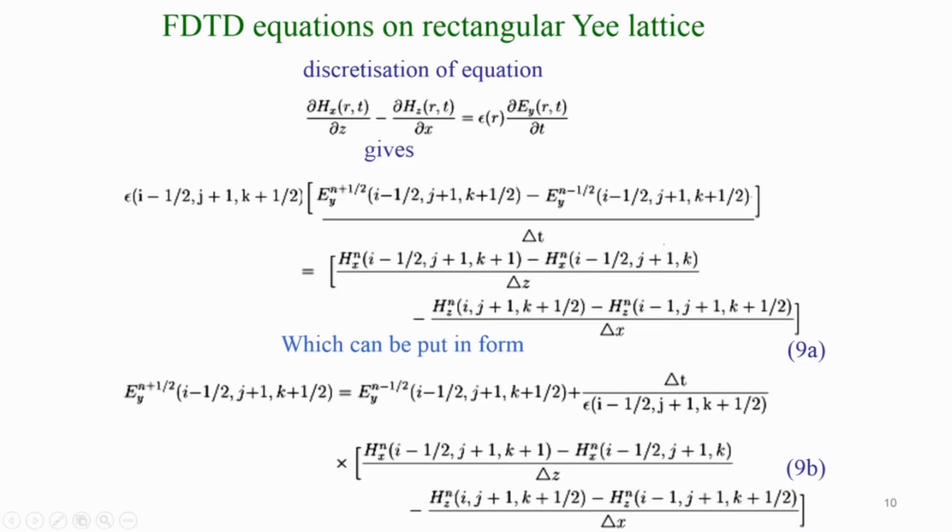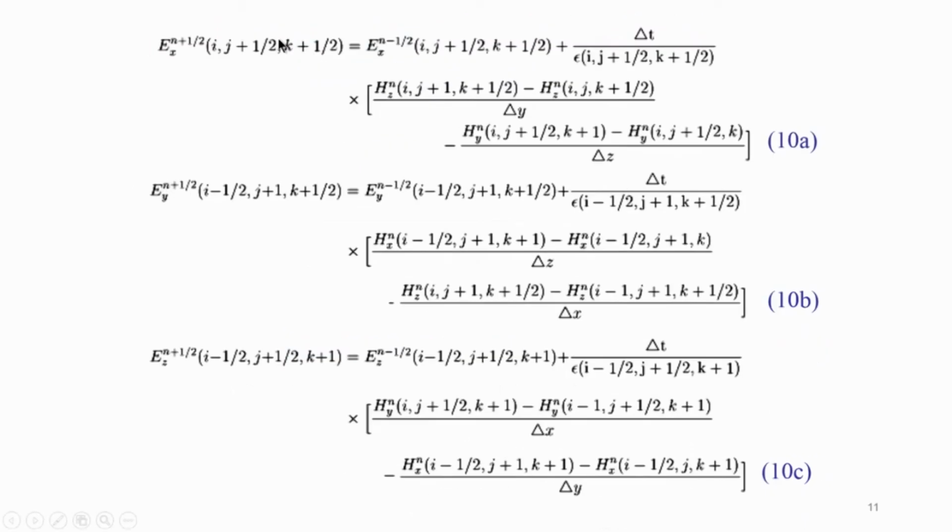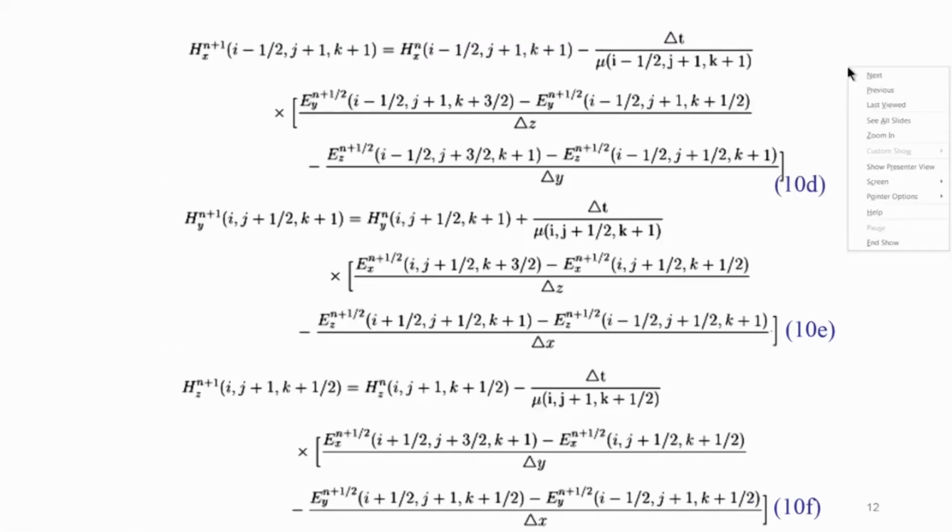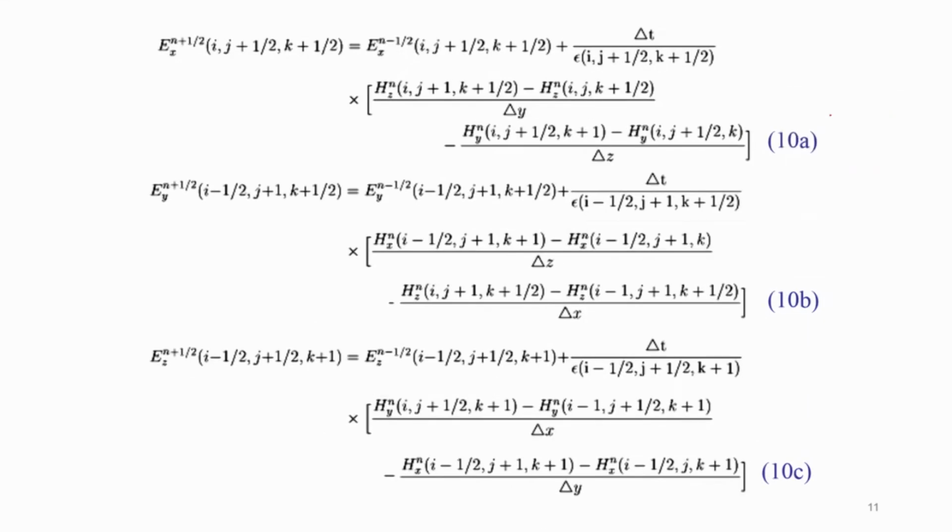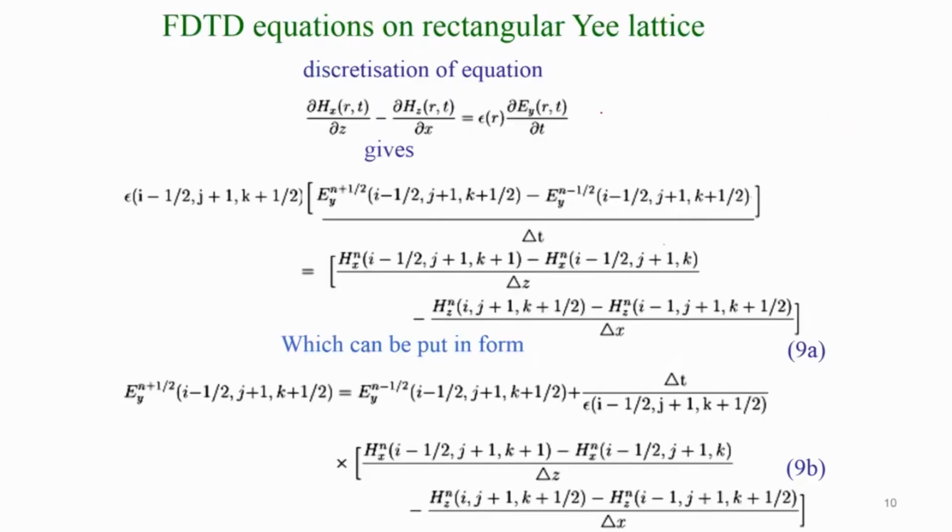So, one of the most common techniques to solve these photonic band gap problems or the design is the FDTD method, which we have seen earlier. We have not gone into much detail about the FDTD method when we discussed the beam propagation method and the passive devices, but I have included here some expressions which could be directly used. You can also find these in some books and current literature.